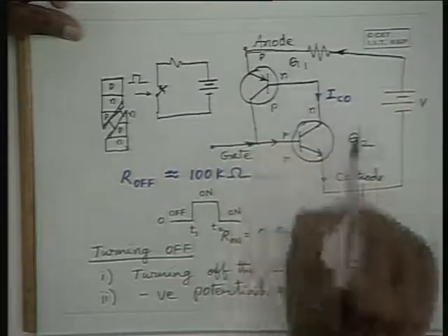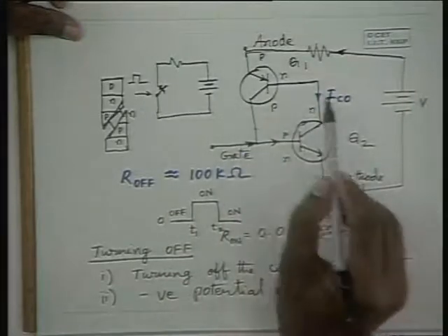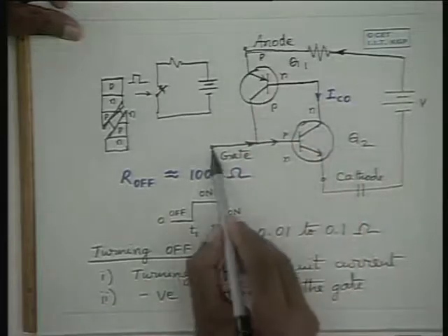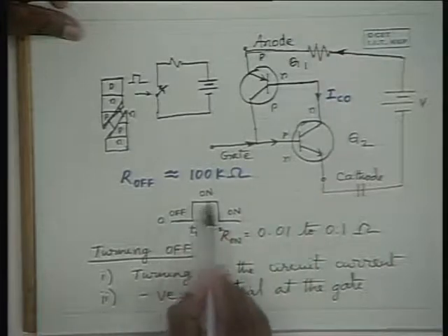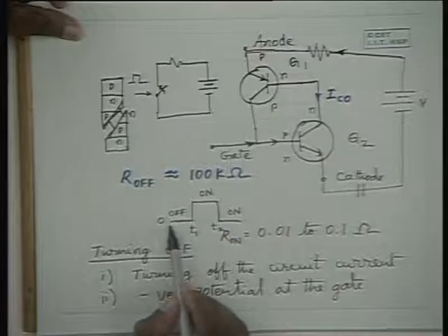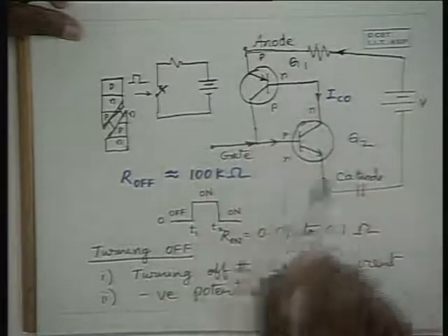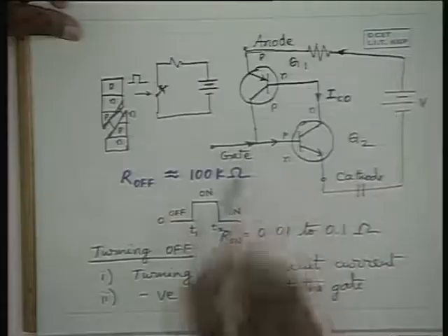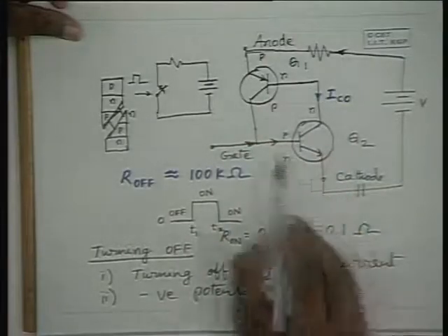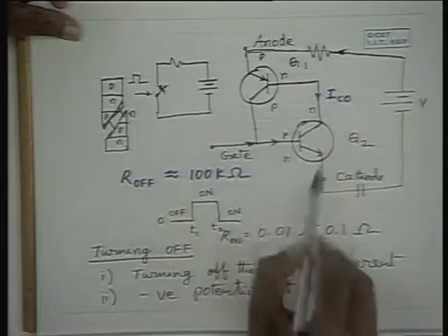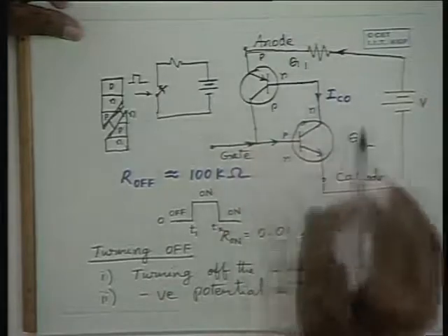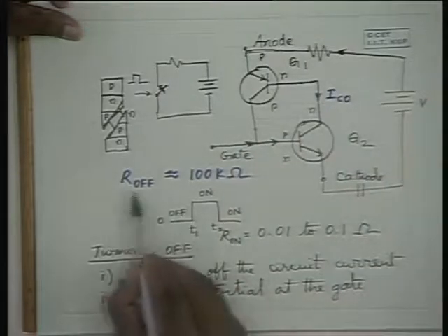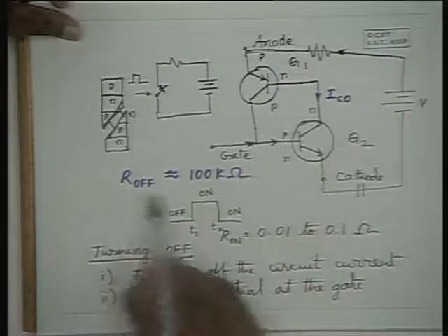Hence, this goes off. And when this goes off, even if this is connected, in the absence of a positive potential here, it acts like what we had before t equal to T1. That means it is like a relaxed system, and when no potential is applied, that means initially when the current is 0, because of no current, no base current and no collector current except for IC naught, this one remains off, and it offers a high input impedance, of the order of hundreds of kilo ohms.